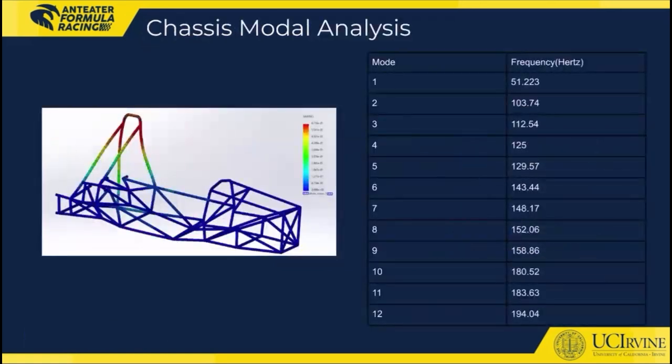The race car will experience frequencies of 3 to 300 Hz on the racetrack. The actual resonant frequencies will be much higher than these values listed in the chart, allowing the race car to perform on the track. The chassis will be weighted down by the driver, engine, etc., and it is made out of tubing rather than beam elements. The solid brick simulation would only work if we treated the tubing as beam elements, therefore reducing the resonant frequencies.